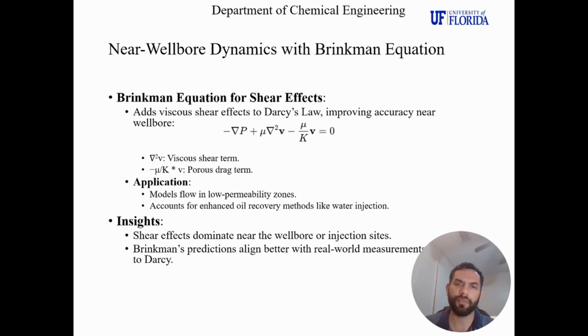This Brinkman equation is crucial for low permeability formations like shale or when enhanced oil recovery techniques such as water or gas injections are used. So the Brinkman equation predicts flow more accurately than Darcy's law under these conditions.